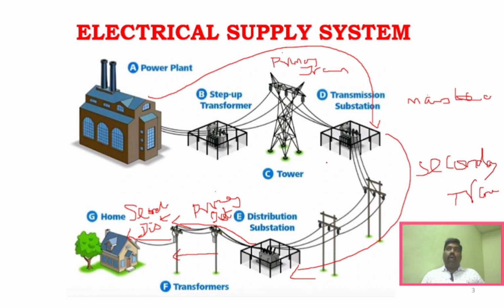Right? And for all this operation, you will understand there is only one step-up transformer that will be used, right? So that is used at this particular place, that is in the primary transmission. When the power is generated, it will be stepped up to a higher voltage and transmitted, right? The power will normally be generated at 11 kilovolt. You have a lot of voltages, but remember any particular voltage and stick to that so that you can explain the complete structure with that particular voltage.